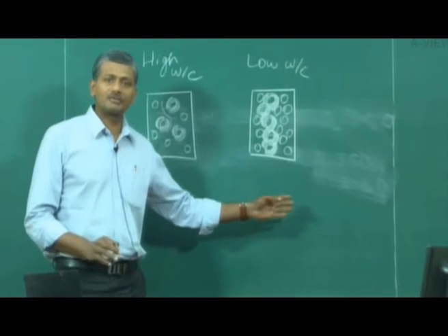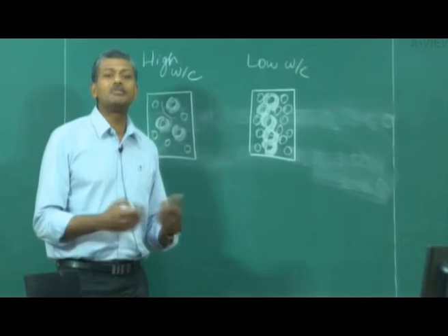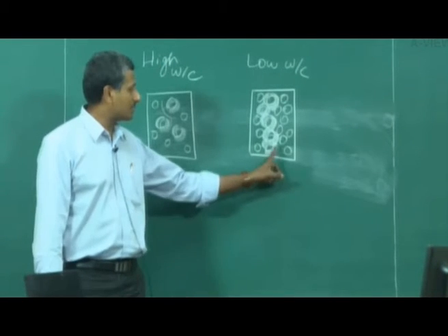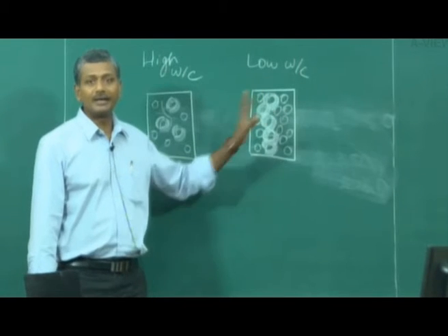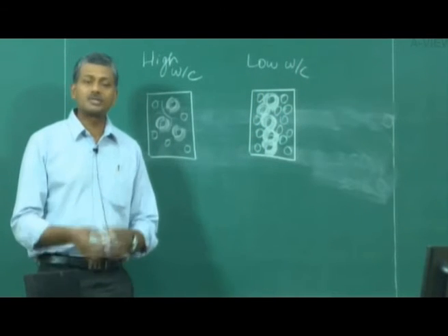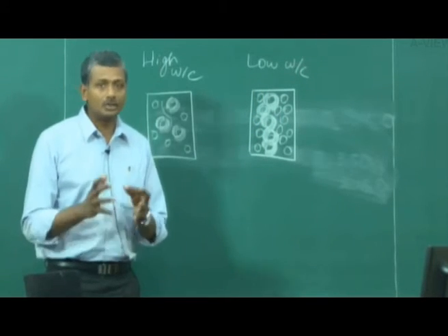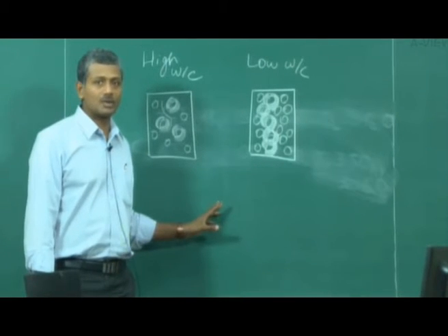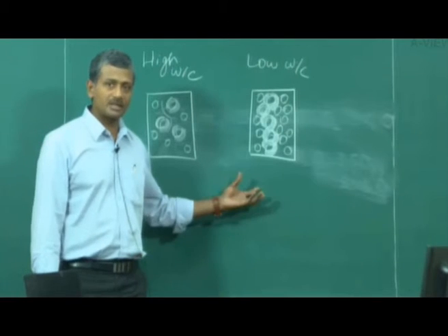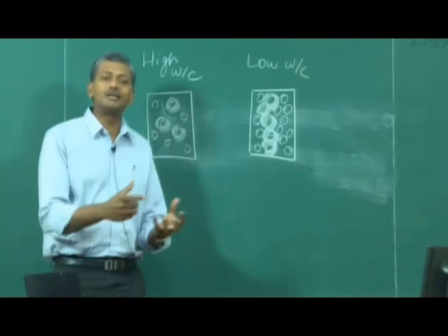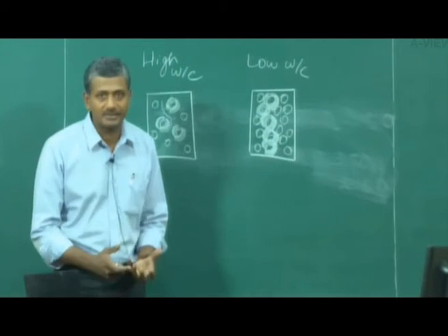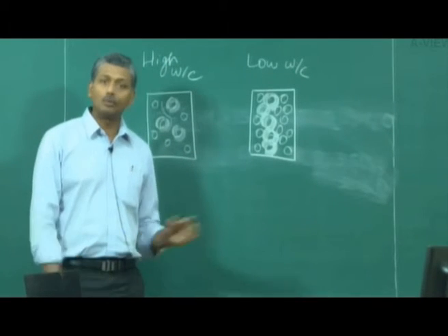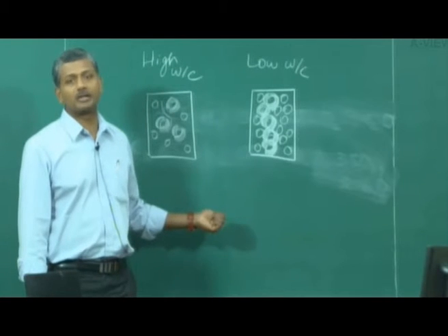The remaining part of the cement which is not hydrated is simply filling up the space and working as a filler. All I need is this hydrated structure network to form, and that produces the necessary degree of binding to give me my required strength and durability. So this is a very crucial concept for you to understand, because when you have more cement particles in a given volume, you are able to create the bridges of hydration products much faster, as a result of which you get much better rate of strength development and overall much better strength and durability in the long term.